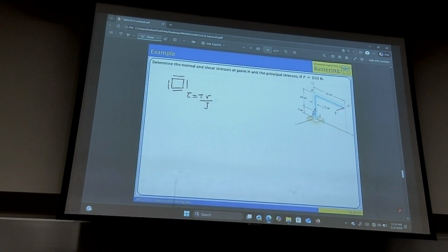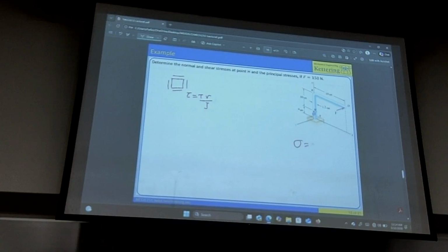The axes are, this one is Y, this one is X, this one is Z. This component, as you load it like this, bends or curls around each axis. One was torsion, it was talked about. X. X, yes, it bends about X. The stress will be in what direction? So you said MC over I, that's bending. You said about X. All right, these two get X. But the stress will be in what direction?